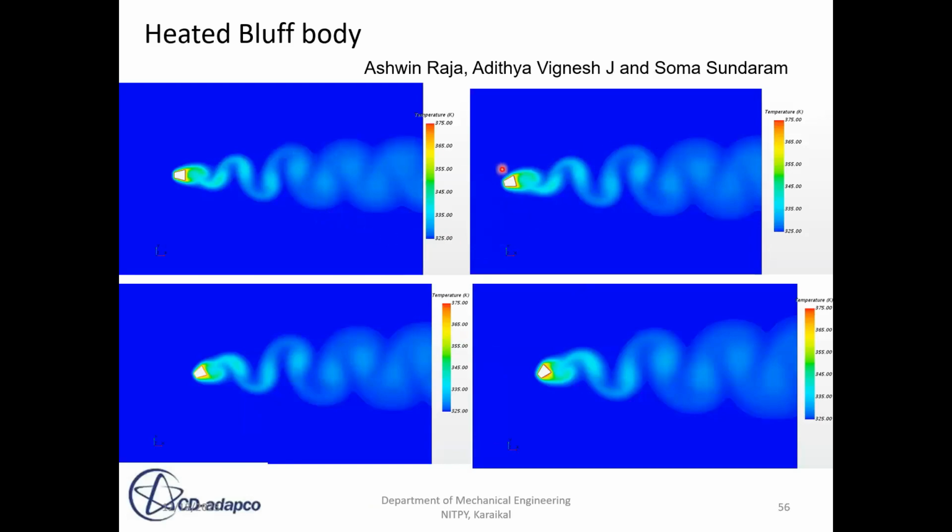And our classical bluff body problem, as I mentioned, this is the kind of result I'm expecting. But when you get a constant shape, that means you have to run the simulation for a longer period of time. So you must be careful.